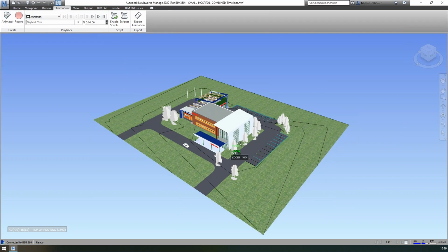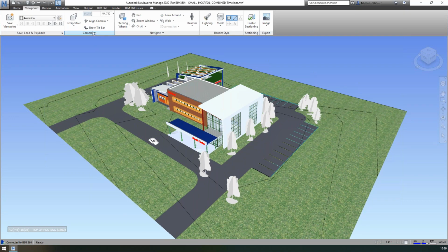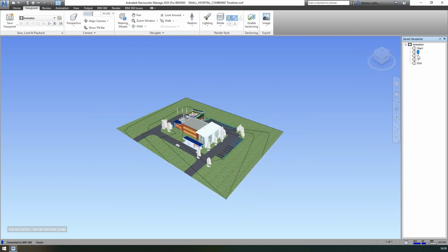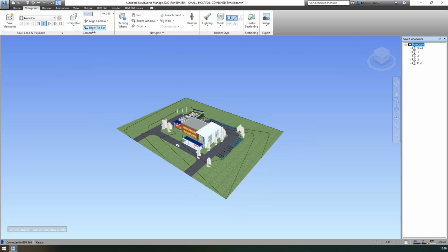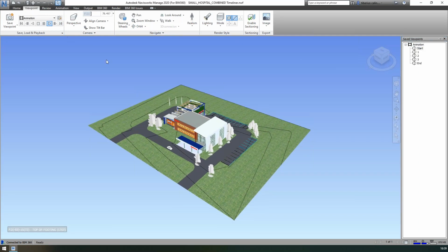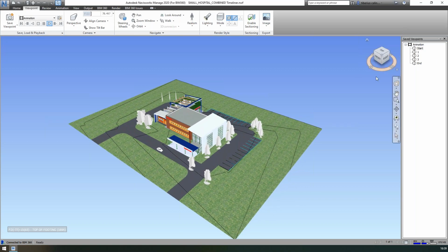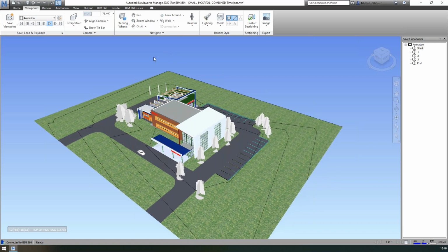And this is the simplest one, where literally you just dock the viewpoint screen, make a starting point and key points within, and then add those to an animation. When you say play, the system just navigates between the viewpoints that you made, so it creates frames in between.